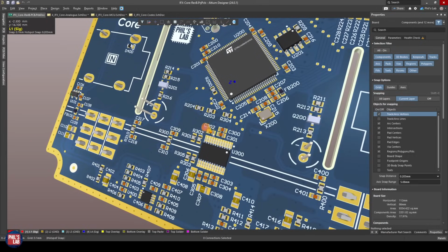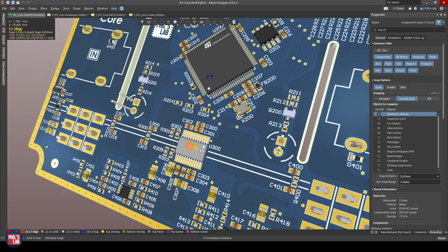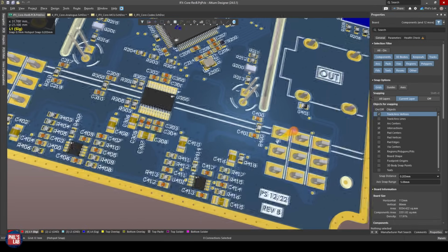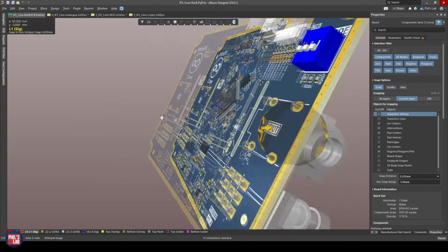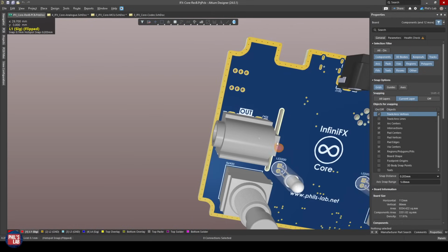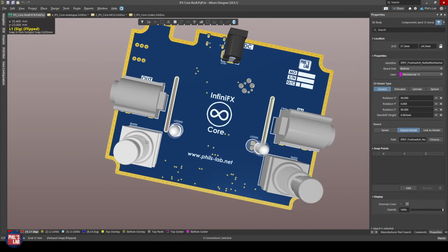And then we have an I2S stream that feeds the STM32H7. We can do some processing on board, and then again an I2S stream that feeds out to the codec DACs, through an analog front end, filters, buffers, and so forth, and that gets sent to the output jack, which is again just a 1/4-inch jack, which could go, for example, to an amplifier. I do also have these 2 foot switches. The one on the left is actually a true bypass control, so I can completely bypass any of this digital system and any of the buffers, so I get a straight feed from input to output.